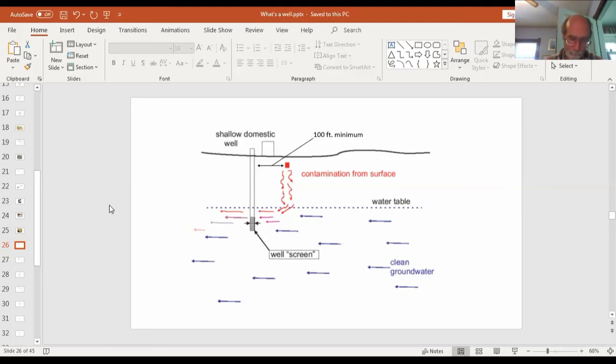Those missile silos over at Cheyenne, you may have heard the stories. They used these solvents to clean those back in the 60s, TCE, trichloroethylene, which is a sinker. And that's why they have air strippers on the Cheyenne municipal water supply to try to get rid of that, because to get it out of the aquifer is really hard.